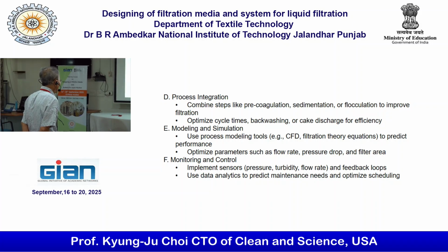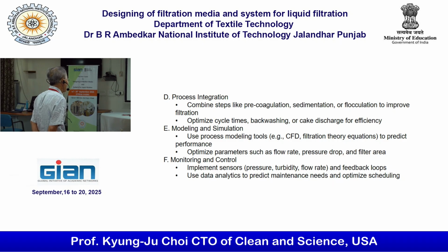Process integration: combine steps like pre-coagulation, sedimentation, flocculation to improve filtration. Optimize the cycle time, backwashing, cake discharge for efficiency. Certainly modeling helps. Modeling and simulation help. I believe this is the current trend. So for the optimization, find out criteria. Currently, the CFD model is quite popular. Once you have modeling, then you can easily find optimal conditions.